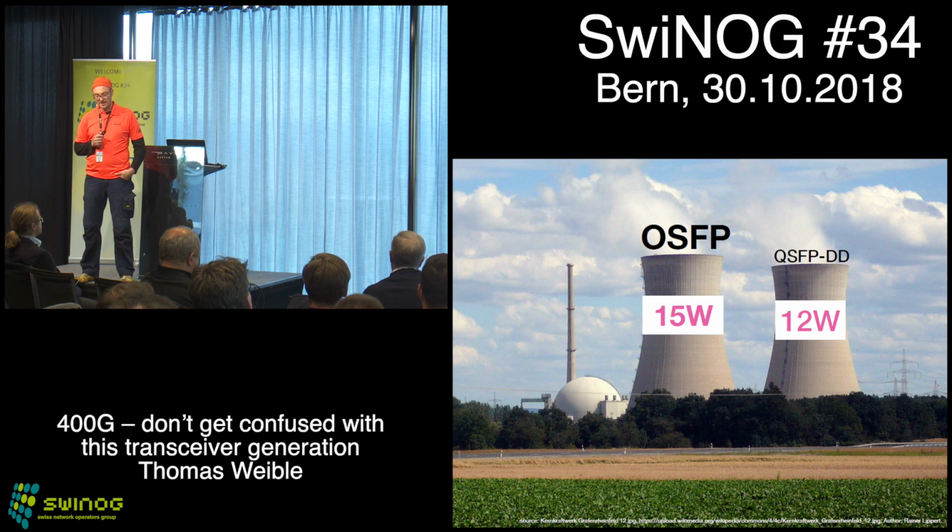When you compare a QSFP-28 for 100 gigabit, which was rated up to 5, 6, 7 watts, now for the 400 gigabit ones we go to 15 or even 20 watts. Why is this so important? We want to build in there the latest technology and also exceed that 10 kilometers landmark, or 25 kilometers for ER4 distance.